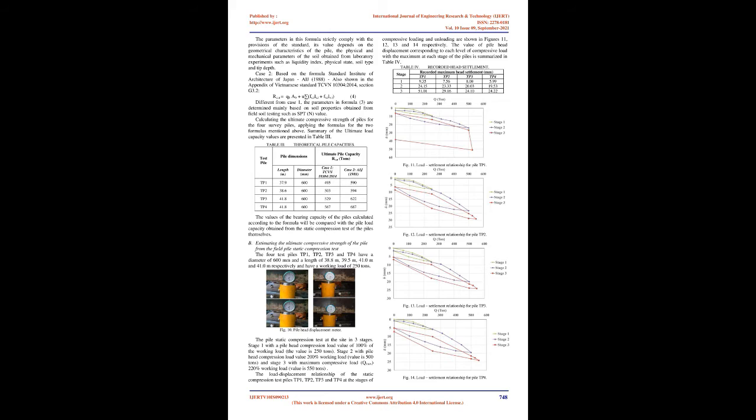Accordingly, in the proposed method, the loading test curve is plotted against settlement based on the result of the load test at the observed location. Lines are drawn from the selected settlement points until they cross the curve. A vertical line is drawn until it reaches the loading axis. From the cross of the load, a line with an angle of 45° is made until it crosses the next line.